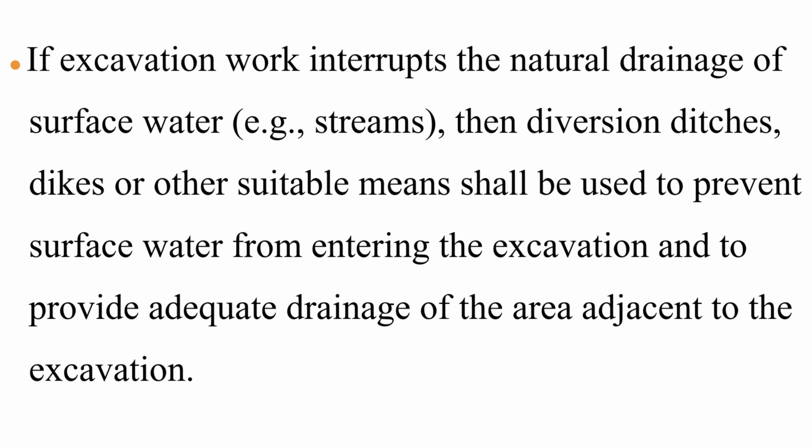If excavation work interrupts the natural drainage of surface water, for example, streams, then diversion ditches, dikes or other suitable means shall be used to prevent surface water from entering the excavation, and to provide adequate drainage of the area adjacent to the excavation.